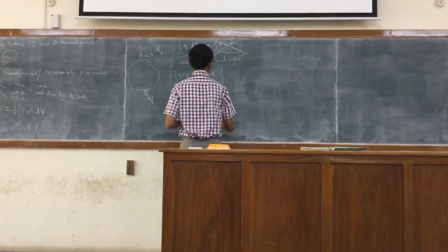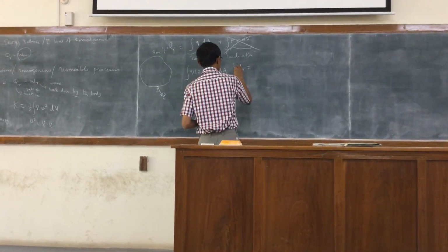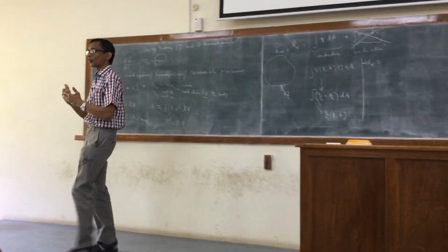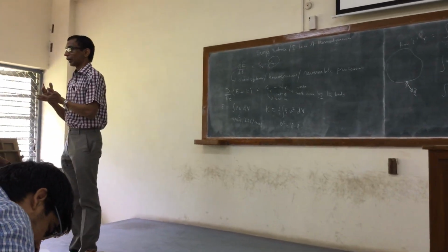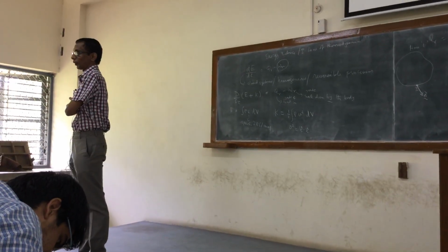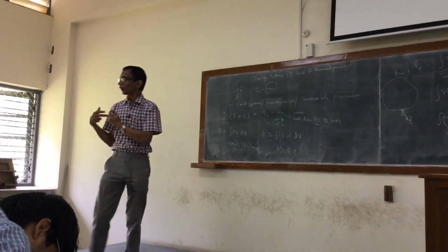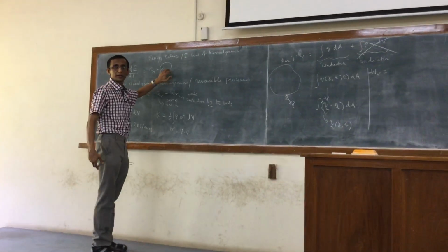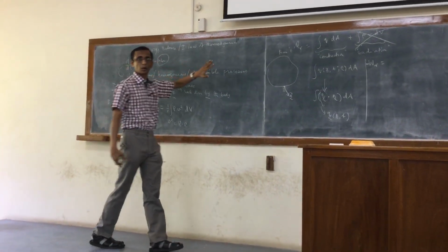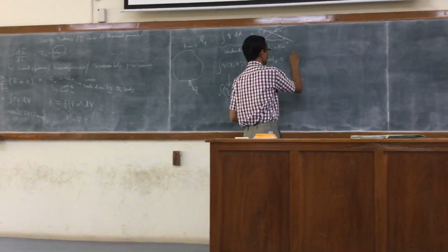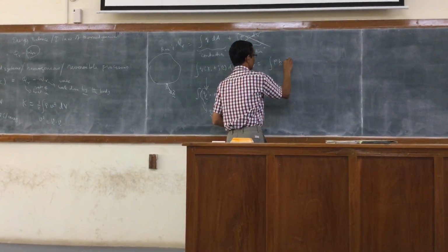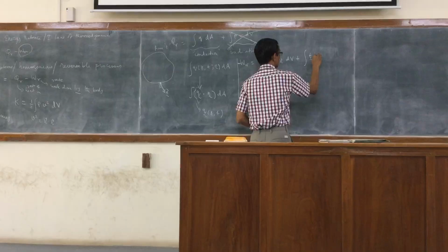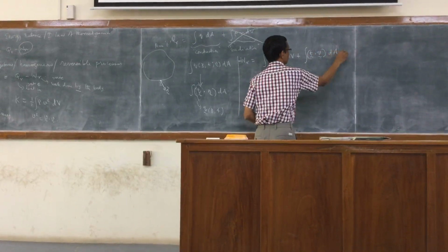So we may obtain minus WR, because when we talk about the body force and the stress force, we are talking about force exerted on a particular body by the fluid outside the body. Right? So we are really talking about work done on the body. Since here WR is defined as the work done by the body, minus WR would be work done on the body, and that is equal to the integral of rho b dotted with v dV plus the integral of t dotted with v dA.